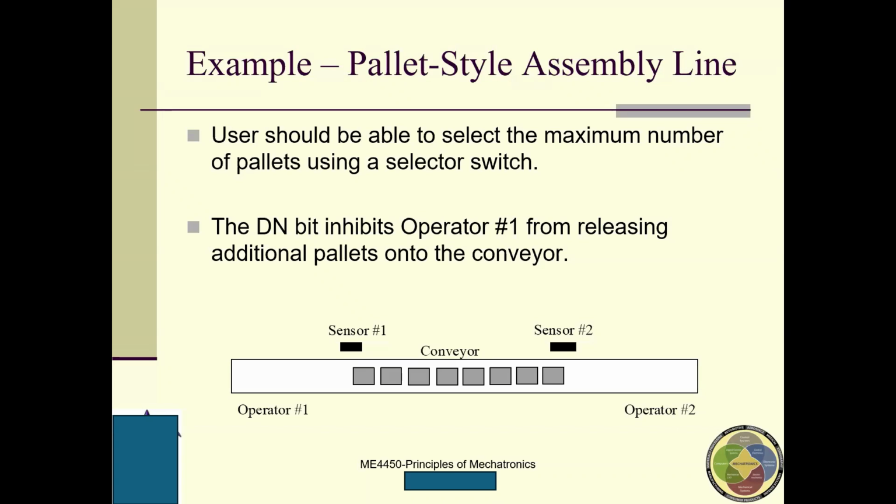Hayden, okay. For CTU and CTD, are those changing the same counter or do they have two different counters? Same counter. Each counter has both CTU and CTD. It depends on how you wire them. Not wire, I should not say wire, because it's how you connect them using the ladder diagram. Not hardware, you do not physically wire them. You just specify them in the ladder diagram. Good question.